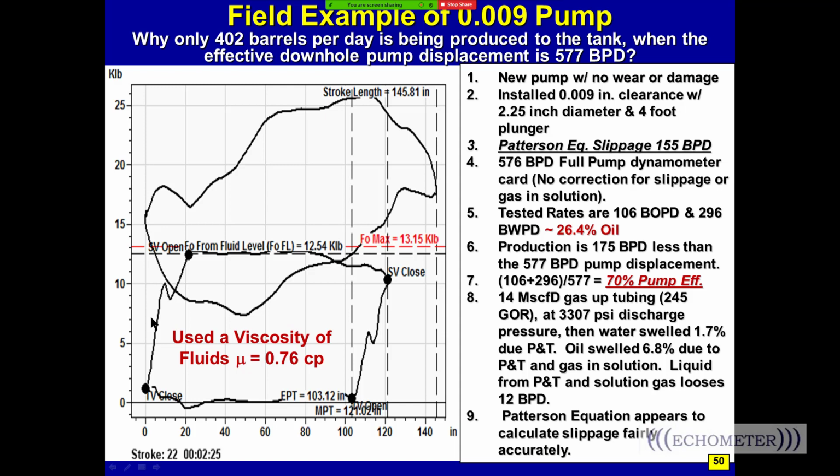And so this is a complicated shape here, and it shows up when you have large clearances and anchored tubing, and this is a motion. The plunger moves, and the harmonic causes the pause, and the slippage causes the load to start to drop off, and then the harmonic causes it to move again, and that's what that is. And that's a super observant question from Bert Pond. Most people don't see that. So we'll have one more question.